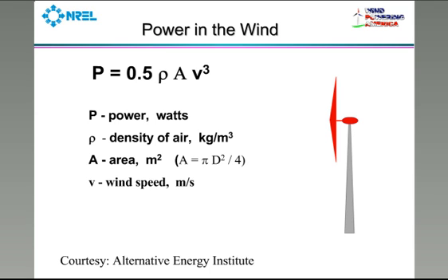And basically, that rotor is your energy capture, and so the energy capture is proportional to the size of the rotor. You sometimes see turbines advertising their sleek, quote unquote, sleek profile. Well, they're basically telling you that they're not going to capture much energy because they made the rotor small. So there's really no point. The V is the important piece.